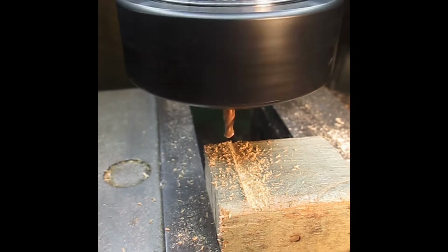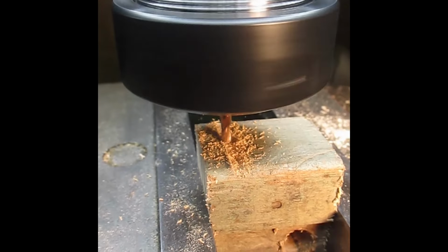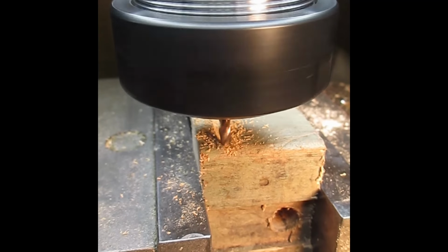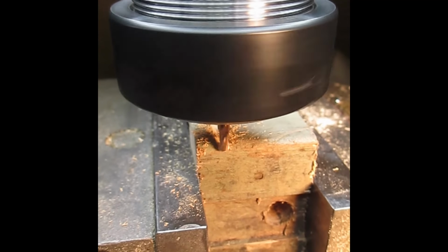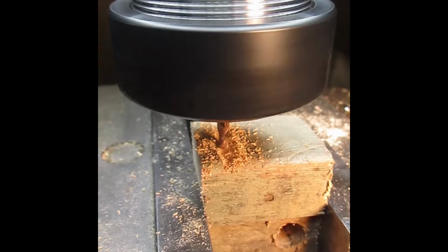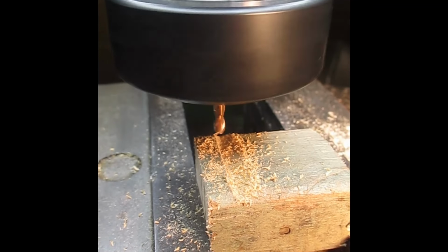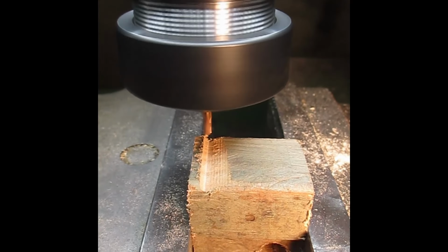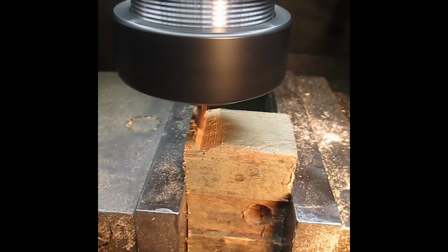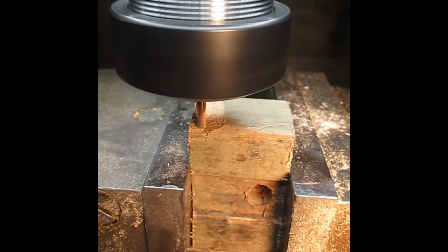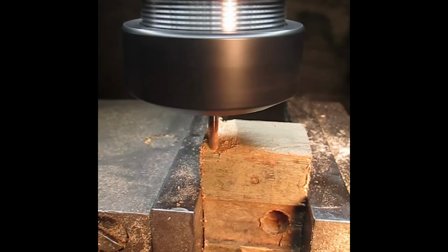Okay, this time I'm going to get into using equations available on the machine to do more enhanced complex shapes. The video is showing the machine creating a face sloping downwards in the y direction. It's using the slotting command to pick down to the depth of that slope, and after it's reached the correct depth it resets the slotting command and steps over by a certain amount to create the next slot.